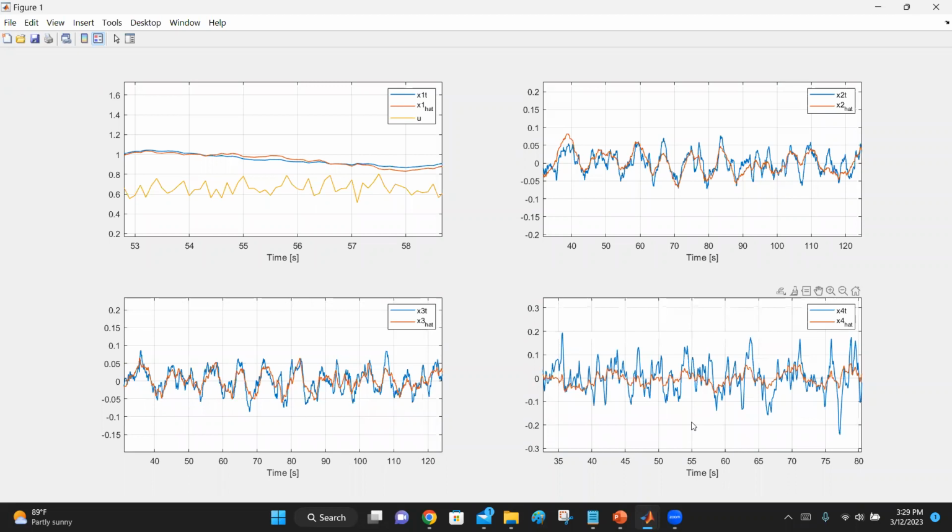Without this filter, you are unable to implement the state feedback because you have only one sensor. It also has some noise. So using that single sensor and predicting all the other state variables, the estimates are used by the LQR for state feedback, and you somehow control the system in a reasonable manner, right? So that's why it's such a celebrated work by Rudolf Kalman in the 60s.